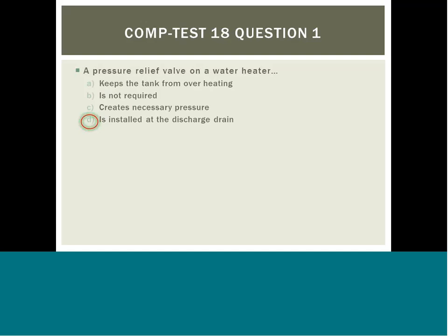Answer A is not correct because a pressure relief valve keeps the tank from overpressurizing. Answer B is not correct because relief valves are required on water heaters, and answer C is not correct because relief valves are used to relieve pressure, not create it.